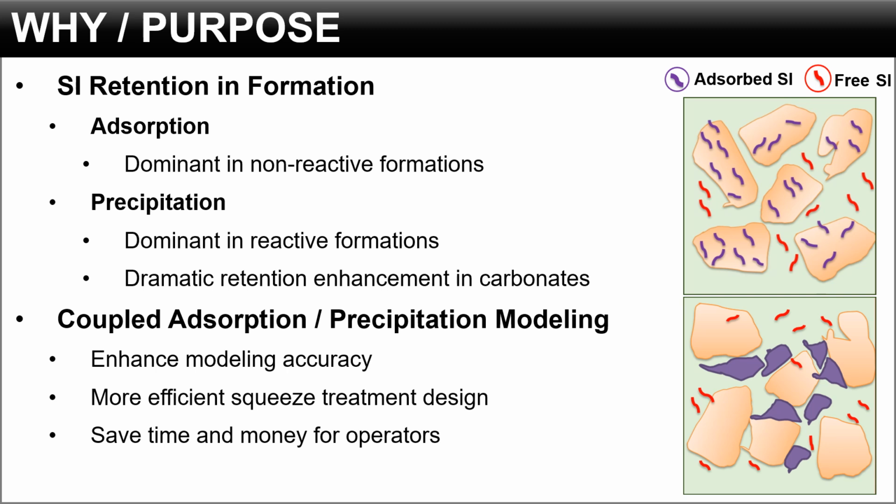So the focus of this research is on the modeling of the coupled adsorption and precipitation actions of the scale inhibitor molecules. We know that considering coupled adsorption and precipitation can enhance the modeling accuracy and the efficiency of squeeze treatment designs. In that way, it can save time and, more importantly, money for the operators or the service companies that are operating the scale inhibitor squeeze treatments.